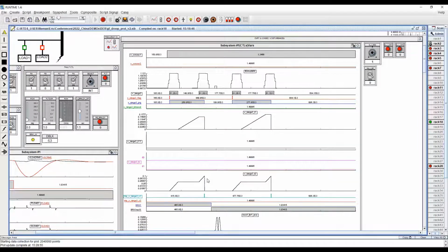We can observe from the result that once the accumulated time of the two consecutive disturbances, which are in one disturbance set, reached 0.1 second, which is the set limit, a trip was asserted. We can see the DR breaker was opened and then the auto reclosing sequence was initiated as expected.